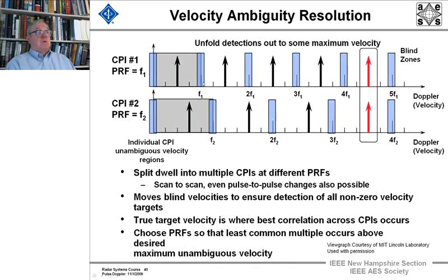You'd start the count of velocity bins at 3, and then this is 4, 5, so you'd start it at 6, 7, and so you'd keep unfolding the velocities after you've done the detections till you see that the detections overlap, and you see out here they overlap, and this can be done in a computer.